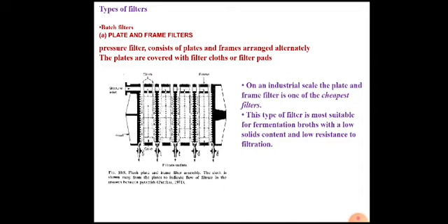On industrial scale, the plate and frame filter is one of the cheapest filters, which is most frequently used in several industries. This type of filter is most suitable for fermentation broth with a low solid content. Otherwise, if it contains high solid content, the filters may get blocked and the filtration will stop.